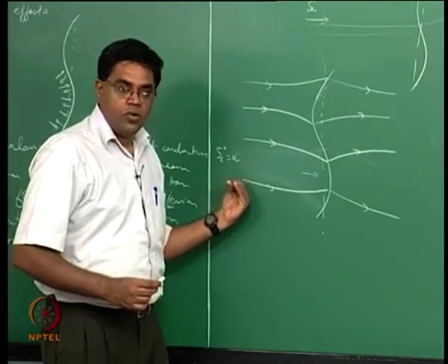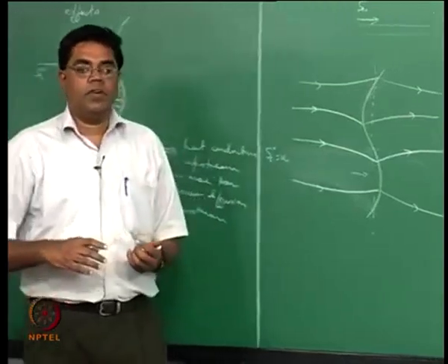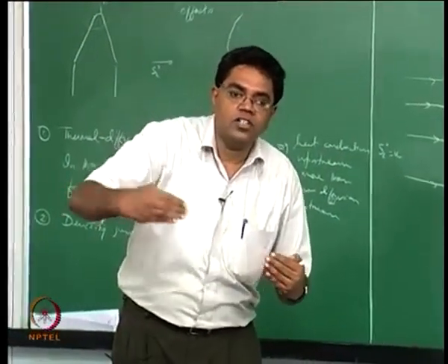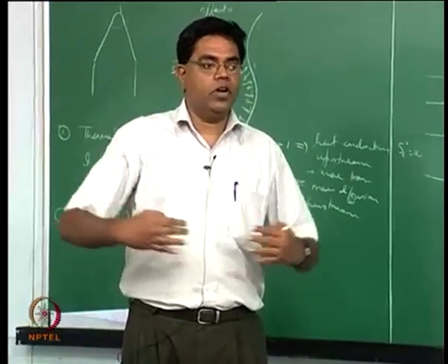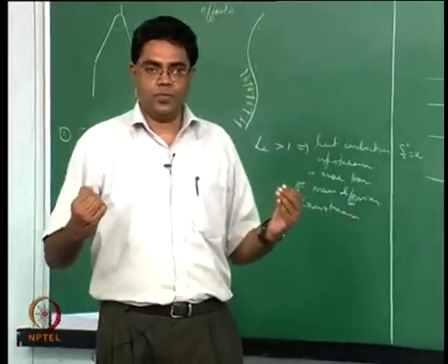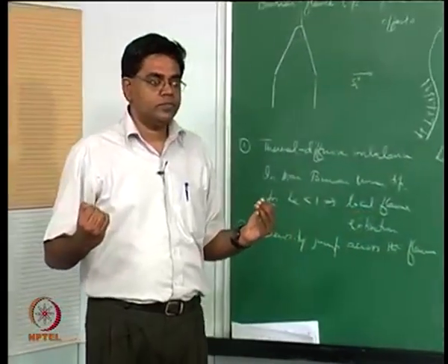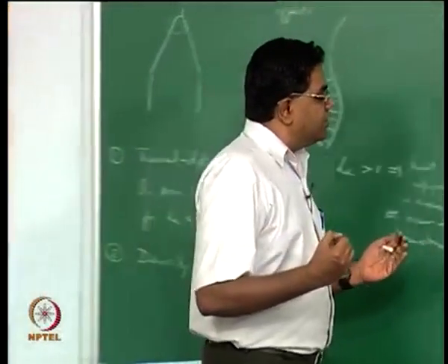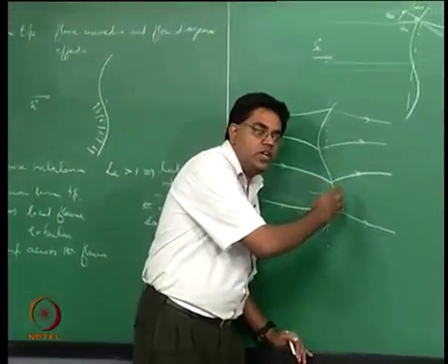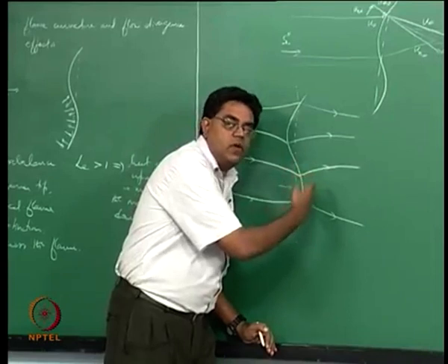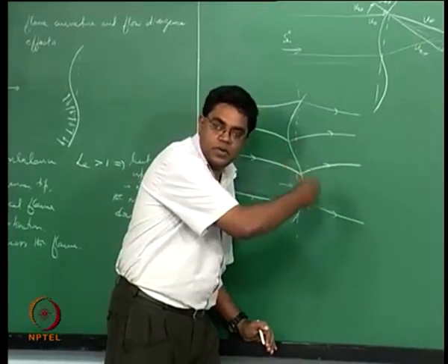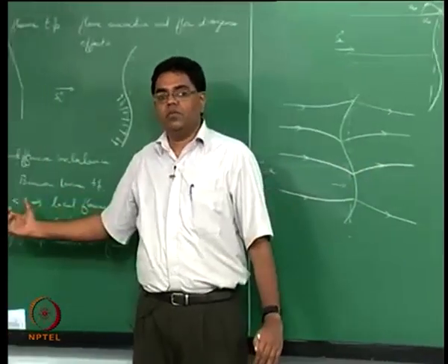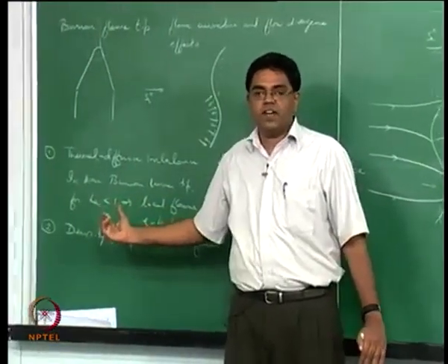So what has essentially happened is the flame has now induced the flow to go faster at it when it tries to have a concave curvature, and this means the flame needs to try to compensate for a higher level of increase in flame speed, which should be by a mechanism that we talked about here if it has to survive.